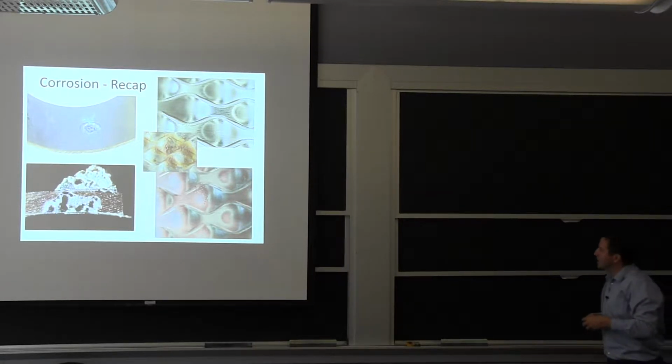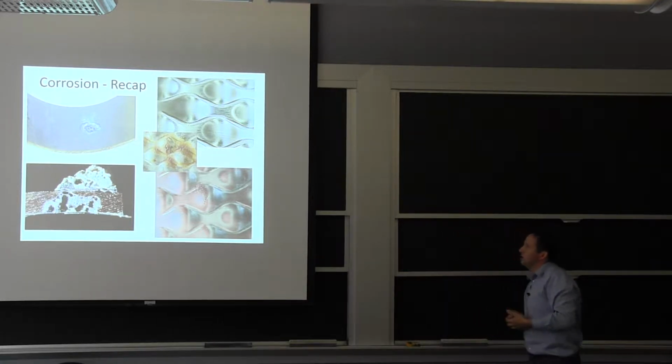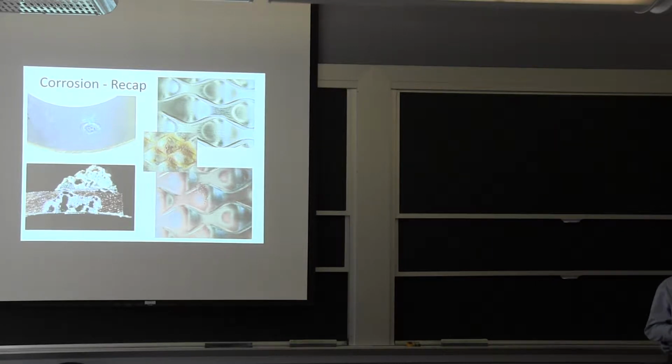So the stainless steel example I had is brushed stainless steel. It became very popular probably the past 10 years or so, as opposed to kind of a dull finish. What happens is you scratch it enough that you don't see the scratches anymore on the stainless, so it gives a more regular appearance. It doesn't show the wear, and you can see the brushing.